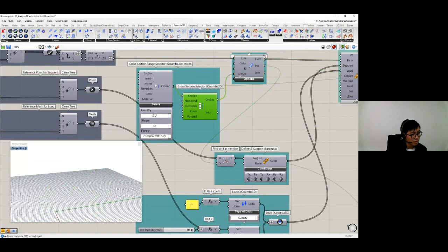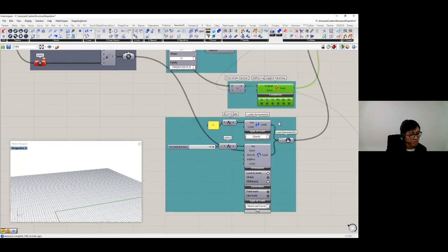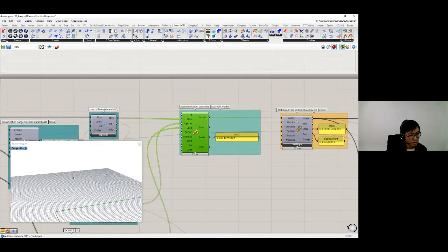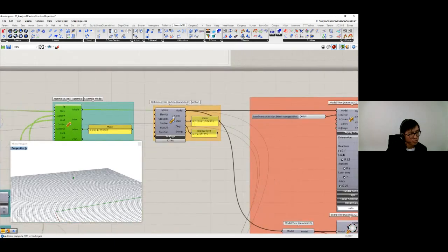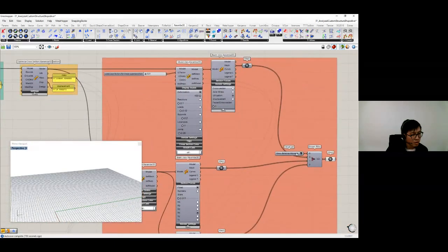So here it's taking one cross section. The supports are taken from the DXF file and defined as supports, and then the loads are defined as a mesh load here with this slider value here, and also gravity. The models are assembled together, and we're once again performing an optimized cross section. In this case, I'm rendering out 3 different types of results with this mesh view here.